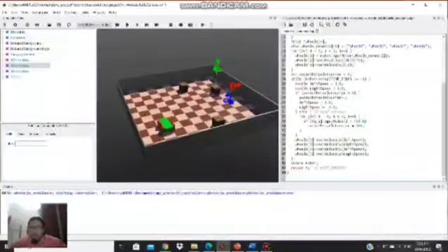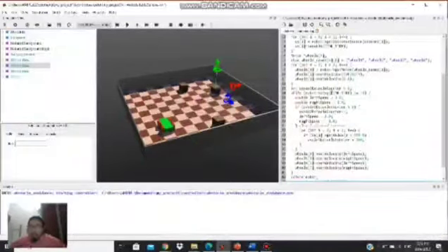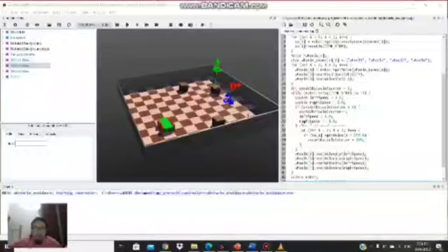And for the obstacle avoidance, as we can see, this is the value that we get: below 950. If the sensor detects an obstacle, it gets a value below 950, and we have the counter, here it is 100 in the counter.